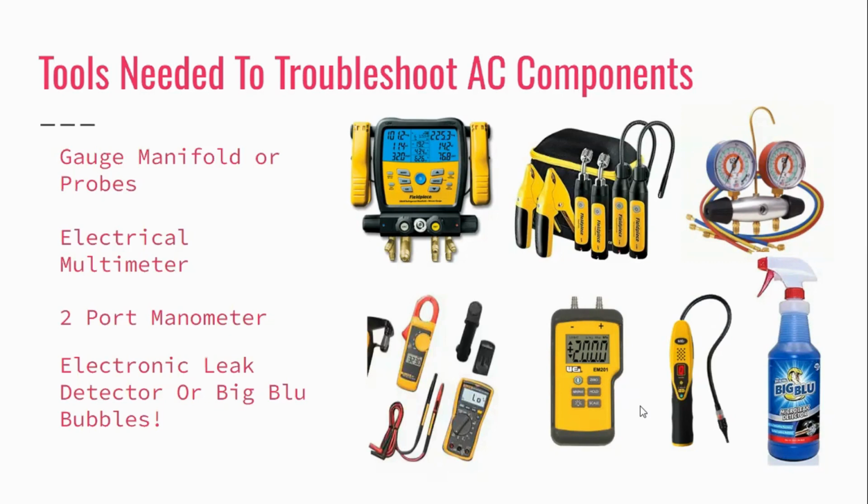And then the last thing is an electronic leak detector or Big Blue. I use both. I use specifically Big Blue brand because we're going to have a show with Viper next week, and that's who makes it. But they are also my favorite bubbles. They feel a lot less like dish soap, and they bubble more when you have a leak. There are some bubble leak detectors that just don't bubble a lot. They'll tend to foam, and it's kind of like, is that a leak? Is it not a leak? But Big Blue is the exception. With Big Blue, you will always see bubbles, and you'll be able to differentiate.